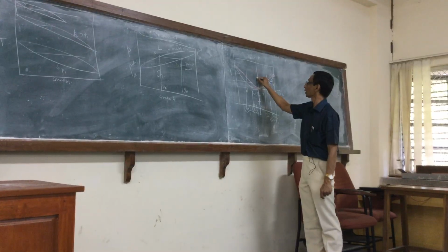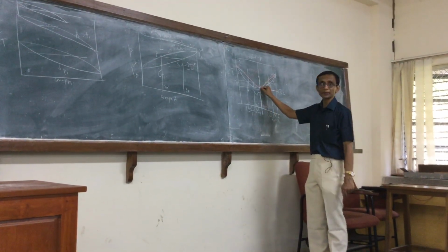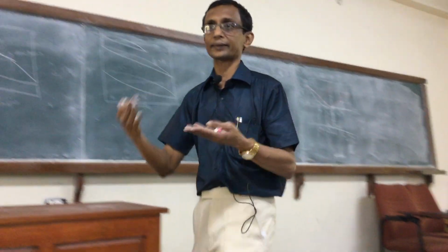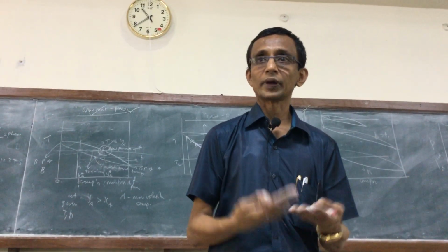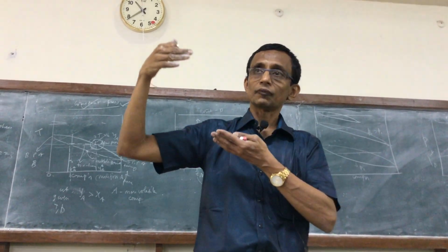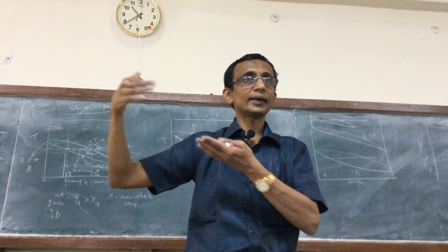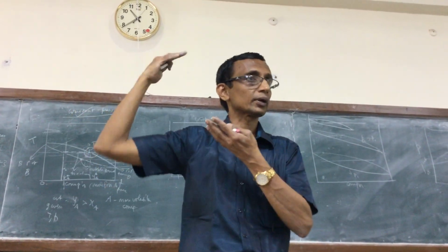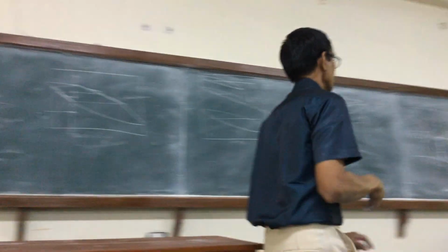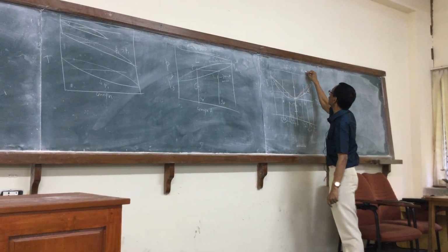After that, it will become a vapor. So what happens at the azeotropic temperature will be coexistence. You might not see it very clearly because their X and Y are both the same, so I cannot plot it differently, right? So it will be a two-phase coexistence at the azeotropic temperature, where XA is equal to YA, and then it will entirely become vapor. So this is somewhat like a pure component boiling, right? This is what is called a minimum boiling azeotrope.